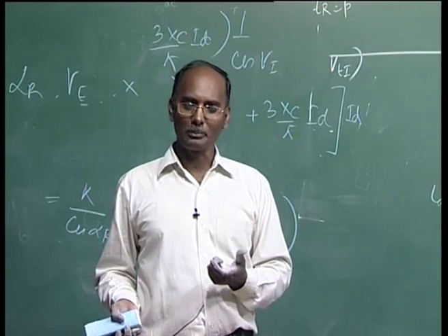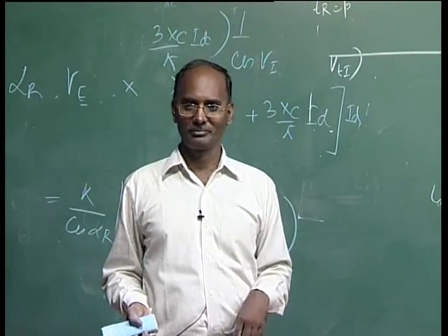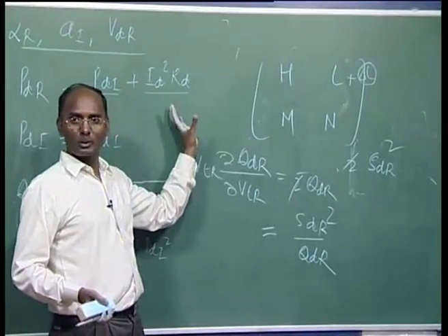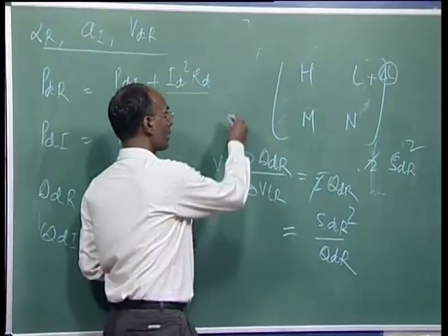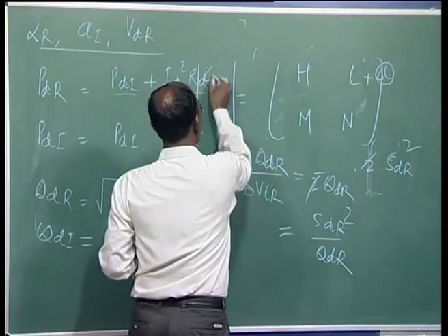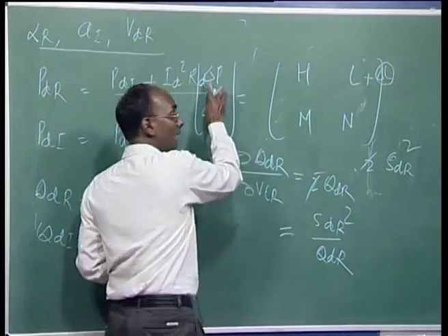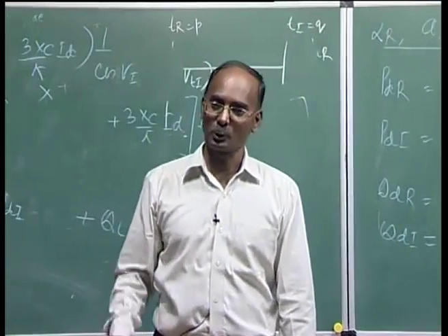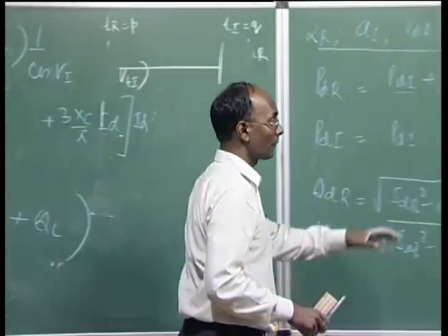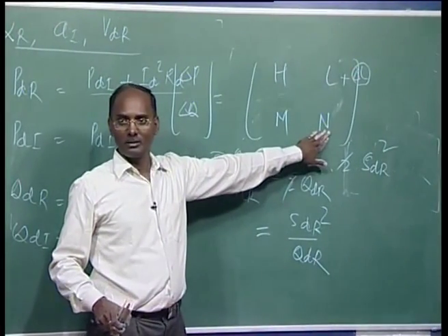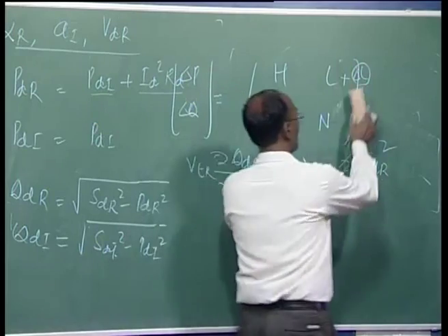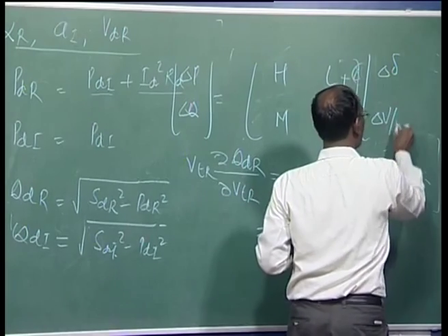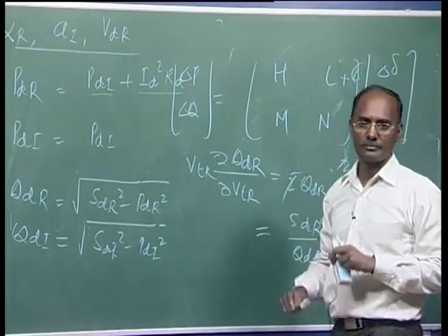Basically that DC term is appearing in terms of mismatch, because every time we are inverting this to calculate those variables, we have del P and del Q. So, in del P and del Q the DC link variables come into the picture, whether you are modifying the Jacobian or not. Then correspondingly we calculate the change in delta and change in V by V, and we solve this equation.